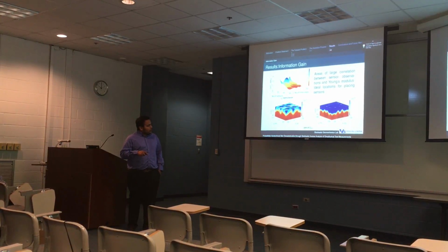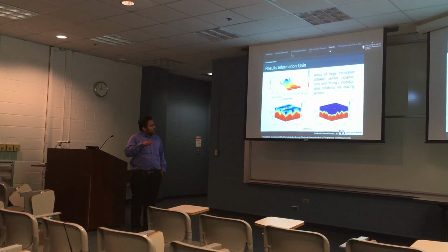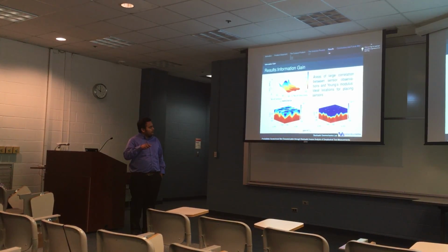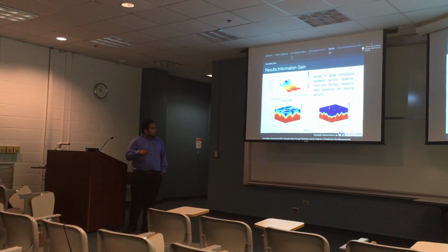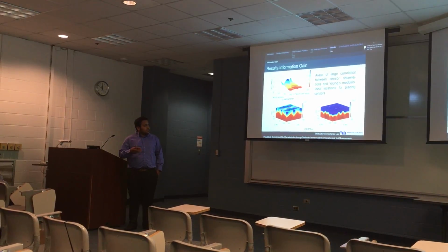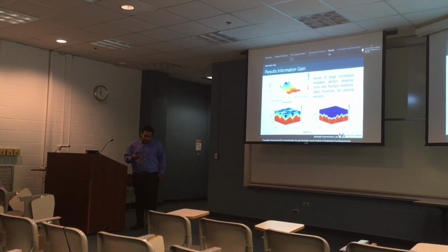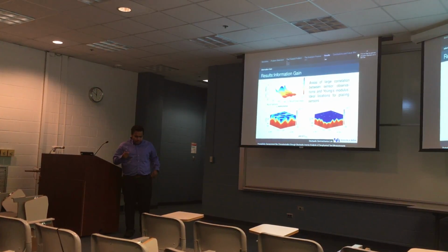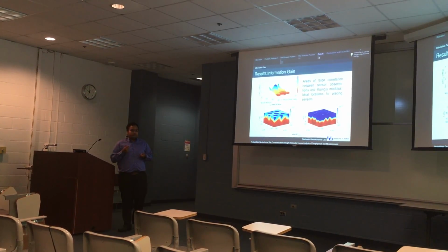However, these results were quite interesting. As you can see, only the sensors located at the top surface give us the maximum information gain. The dark blue region has the highest information gain, and this can lead to the conclusion that we need just put the sensors on the surface of the soil instead of digging deep.